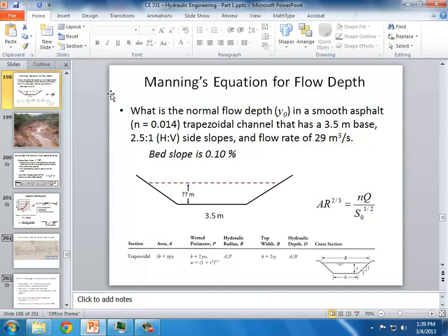If we were doing design and we wanted to know, if it's this channel geometry and we saw a depth of 2, then what would be the flow rate that corresponds to a depth of 2? And it can solve the parameter that's highlighted, and you just click solve. Or if you had 40 that you knew, then you wanted the depth to only be 1.75, then how wide should the channel be? You can say solve for B.